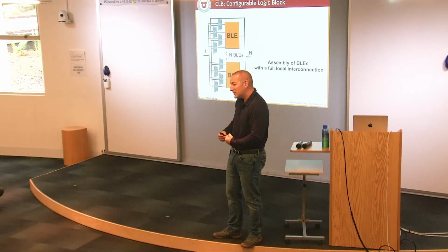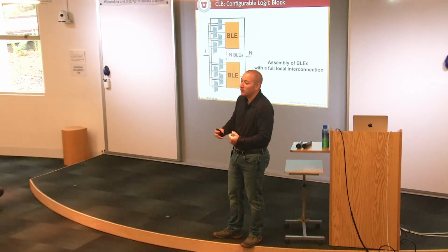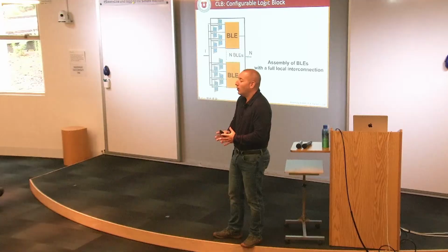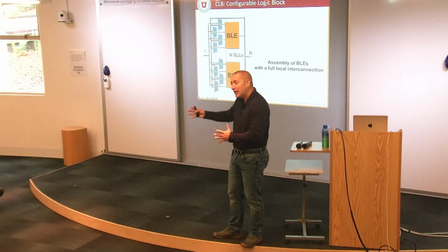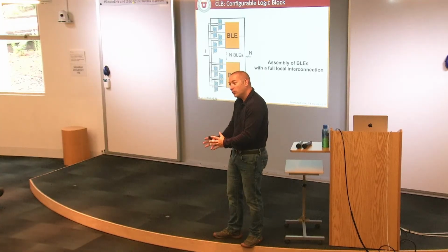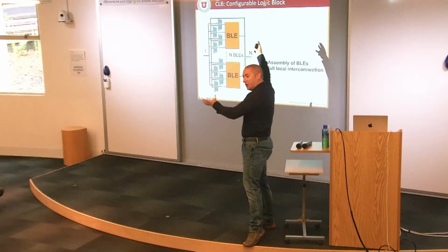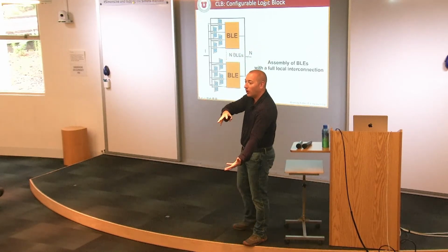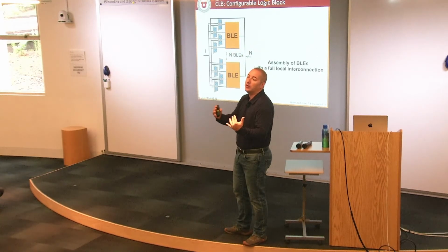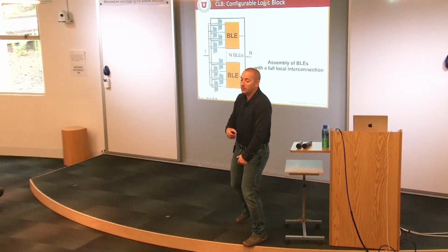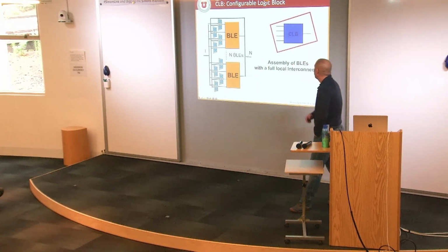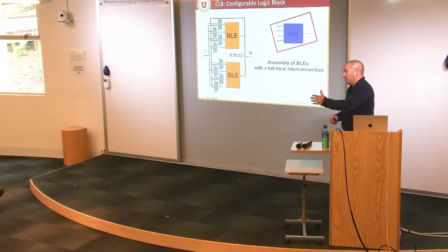Why 4, why 6? It's also linked to logic synthesis, right? It depends on the K-size LUT mapping that you can do for your logic cones. So the bigger your logic hardware, the bigger the cones and the functions you have to find and map to this hardware. So it's a trade-off. Did I answer your question, actually? Yeah, sure. Oh, awesome. Thank you.